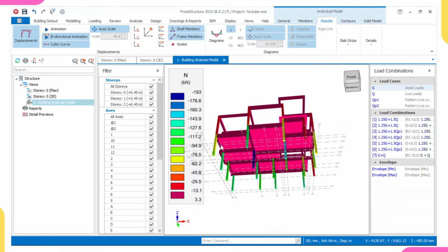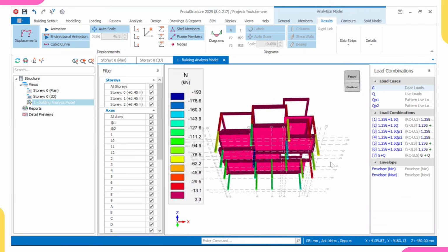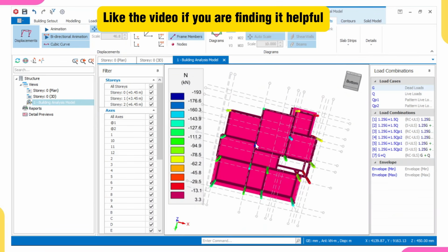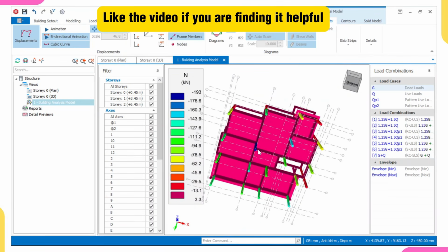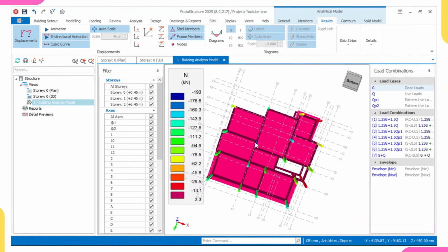The ones in lead and orange are mostly placed at the edges, because they are not really carrying slab in all directions. But these ones at the center are carrying slab in all directions. That's why the load coming to them is high. And this is the one we just designed. The pad base is 1600, and the reason is that the load coming to it is much.